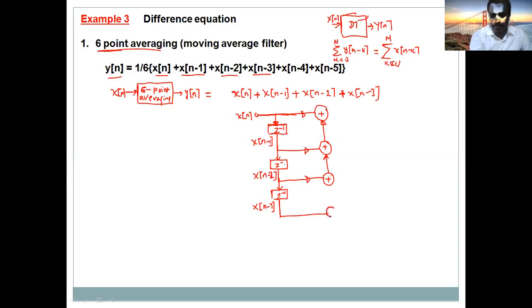So we need an adder. This is the adder circuit. Okay. Any more? Yes. We need also another input, so give it here. This is a delay element. So what will be the output? The output will be x of n minus 4, right? X of n minus 3 delayed by 1, we get it.